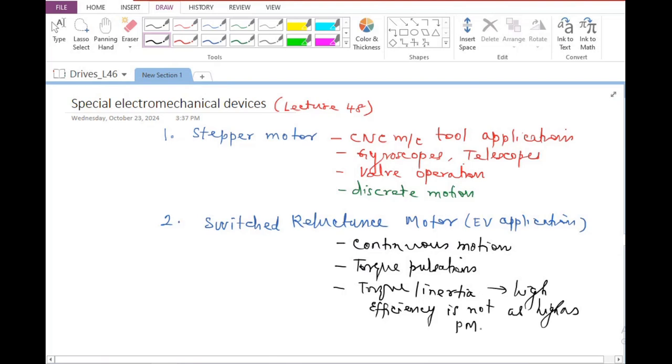And if you look at PMSM that is being used for electric vehicle application, every percentage efficiency improvement results in a reduction of the battery size, which is one of the costliest elements within the electric vehicle. So we have to be very careful about reducing the size of the battery and the cost of the entire battery pack. Or if you employ a PMSM for a given size of the battery pack, the range can be extensively improved even if the efficiency is increased by 1%. So PMSM happens to be the winner as far as the efficiency is concerned.